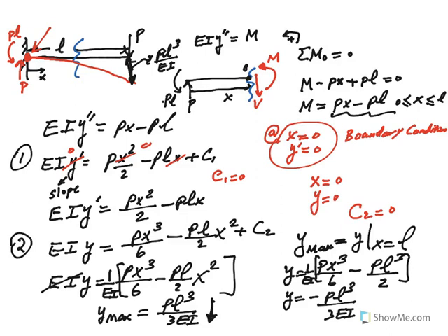You could also use the equation of slope and figure out what the slope is. The slope would be the tangent to this, which we usually denote by angle theta, the slope at x equals L. What I will do in the next lecture, which hopefully would be around 10 minutes, I can show you that you can cut this beam and use the other side. Of course, the equation would be different, but the outcome is going to be the same because you're changing your reference, and this would be your x in that case.